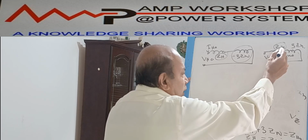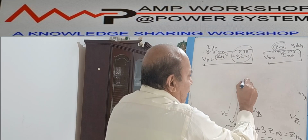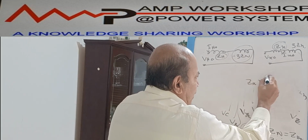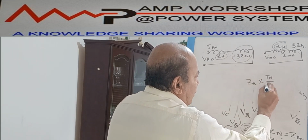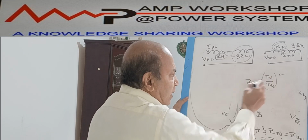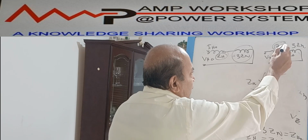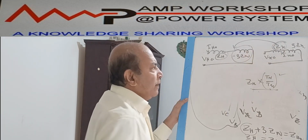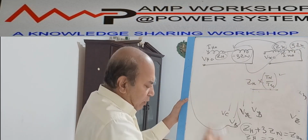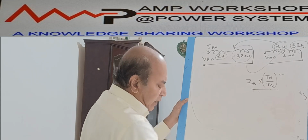We know that if we want to convert from the secondary side to the primary side, we have to multiply the impedance by the turn ratio A squared. That means the primary turns T primary and T secondary, and A squared is our voltage ratio, primary voltage by secondary voltage. We have seen it already. By using this formula, this ZS can be transferred over here. Similarly, the 3Zn we can transfer over here. That means these two networks we can combine together, and we will get an overall zero sequence network.